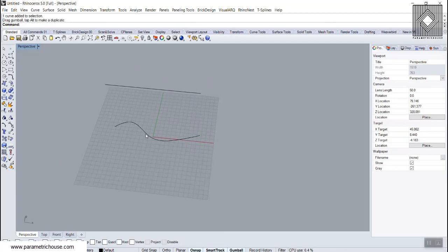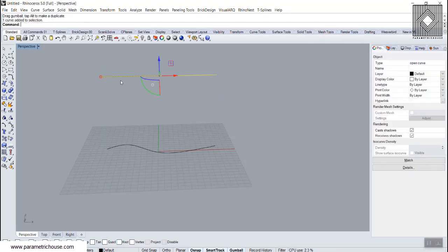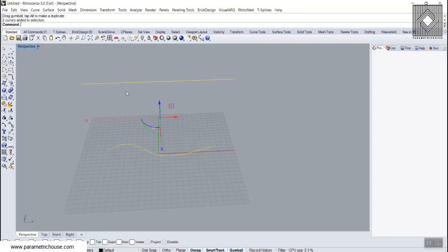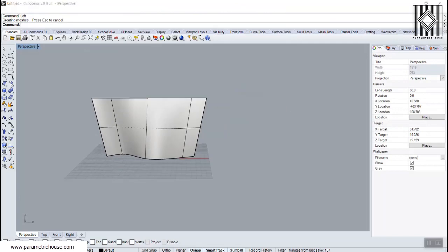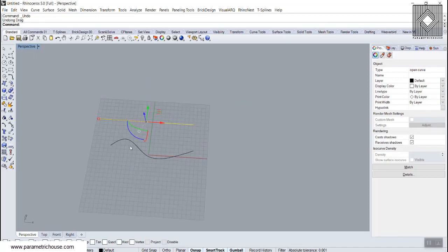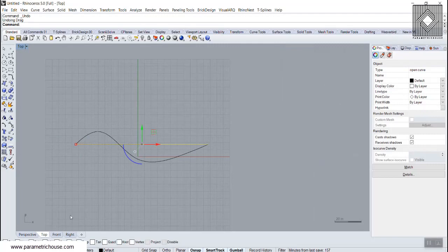You can produce more complicated surfaces, but remember, you always have to have those sections for your surface aligned in just the Z direction. If I scale this up a little bit, this surface is not good for a brick wall because the bricks will sit out from here and will not have a brick underneath them or above. So remember that your sections should be, if you look at them from the top, the same dimensions in the X direction.